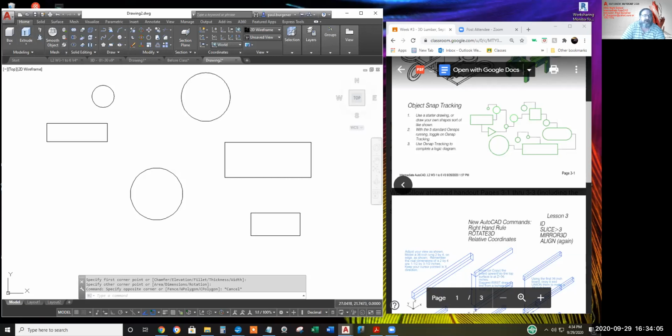Up to this point, you could easily just draw a line excessively long, draw a line from here excessively long, and then trim or fillet it at a 0 radius. But with object snap tracking, it saves you a couple steps. I'll launch the line command. You need to acquire the 2 points as if they're straight edges that magically appear.